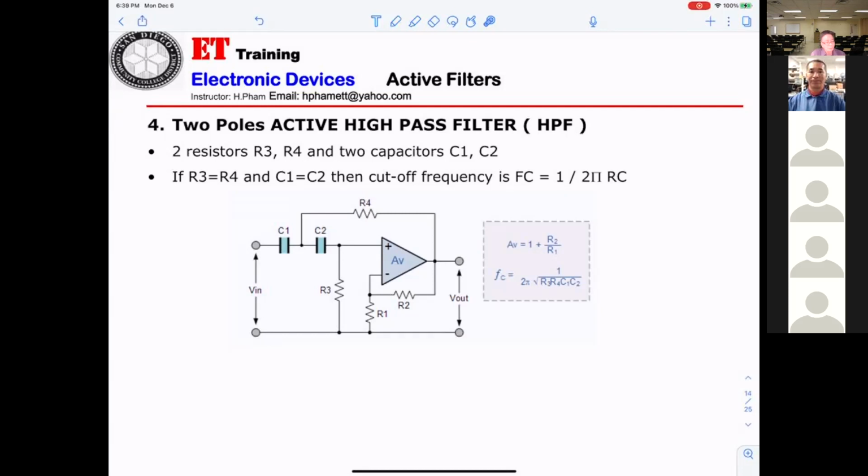When you calculate the cutoff frequency, you have to know which resistors belong in it. That's what I was trying to ask you. If you know this is a non-inverting, R1, R2 make up the gain. The leftover R3, R4 are the passive components you use to calculate the frequency.